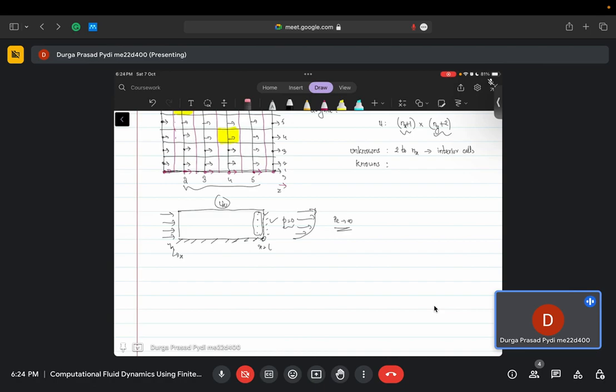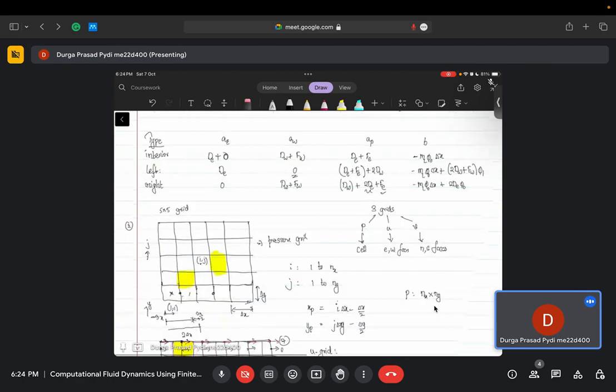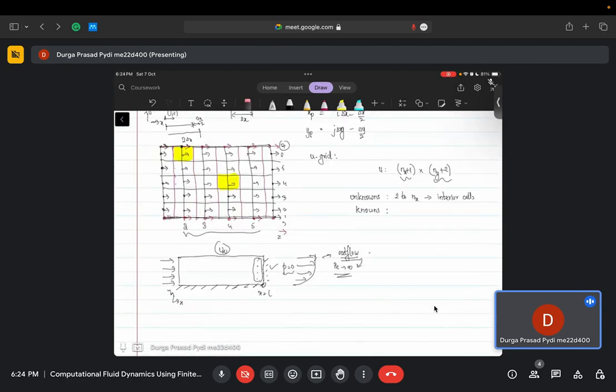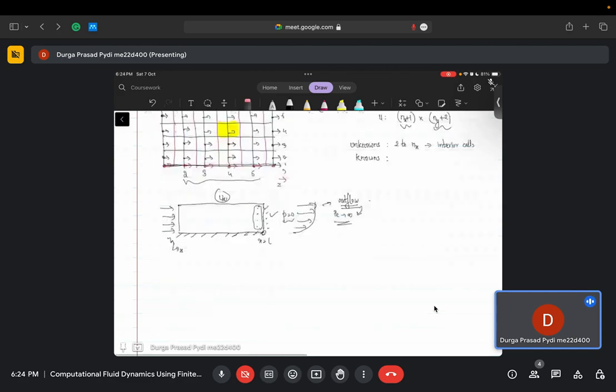So as long as you know that flow is in one particular direction, this is something you call an outflow. As long as you know for sure that it is an outflow, then you can use this high Peclet number assumption, and then you will be able to solve it. That is something that we are doing even here. We are essentially saying it is fully developed, so you have del u del x equal to 0. Instead of saying u is constant, I am saying as you increase your x, your u will not be changing. Whenever you take your domain, the domain should be sufficiently large to include all the effects that you want to consider. Otherwise you need to give appropriate boundary conditions.